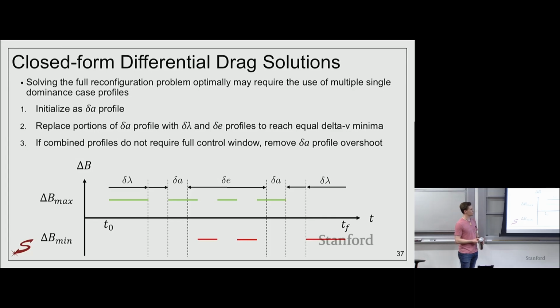So one of the things I skipped over, one of the assumptions for atmospheric drag as well, is that we have a kind of instantaneous change in attitude, because the change in attitude is actually fairly quick with reaction wheels and with small spacecraft. We're not trying to turn the Hubble telescope. We're just trying to turn a CubeSat. So it happens fairly quickly over the span of an orbital period. We haven't done many sims yet for SwarmX to figure out how good of an assumption that is. But not doing that would fundamentally change the control problem in a lot of ways that you could then solve on the back end, but it wouldn't be solving it optimally as simply as this, right?